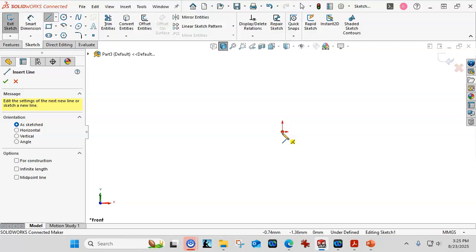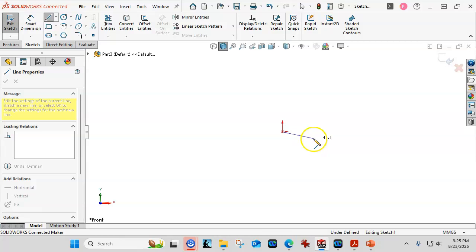All right, so what I mean by that is I'm going to click on the origin, and then as I drag out, it's going to start the line, and we're looking for those inferences. Again, the yellow is now highlighted on horizontal. If we go up, the yellow is highlighted, and it's giving me approximate length. I'm not going to worry about that too much. If it was like, oh, I'm way out here, I don't need to be that long, okay, I'm going to draw it back in a little bit.